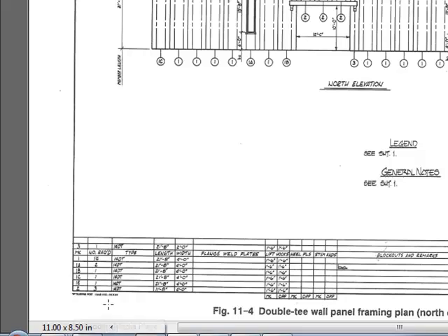So the first thing you would do is gather your raw data for your column framing plan, any information that the architect or the engineer gives you, determine the center lines and all of that. Then you would determine the depth and width of the columns, and you draw them. You would add center lines, column number and letter designations, and dimensions as shown in figure 1113. So that's on the next page. So your drawings will look similar to this, but not exactly, because your assignment is different.